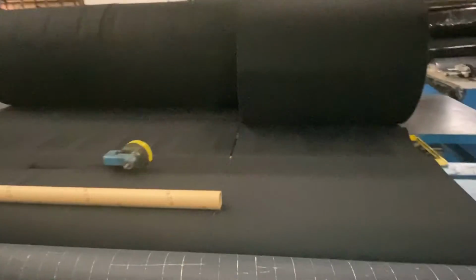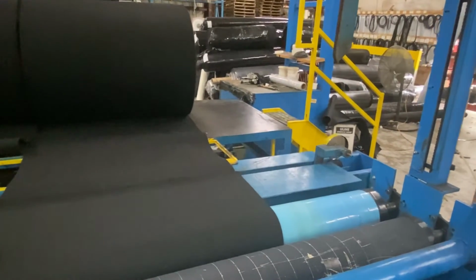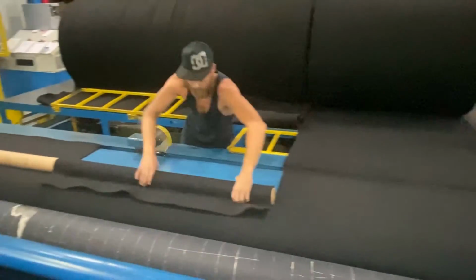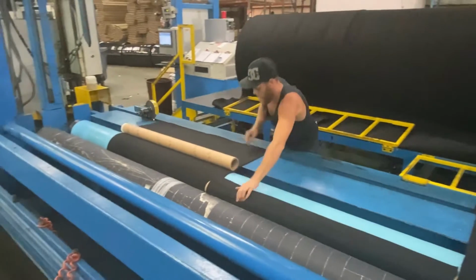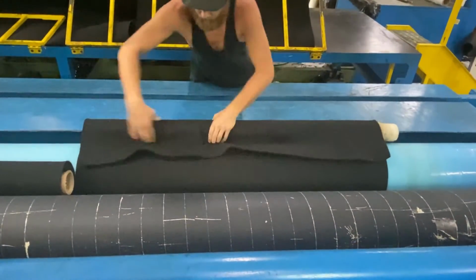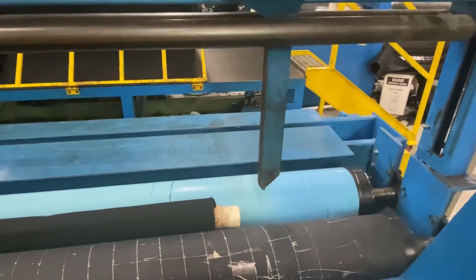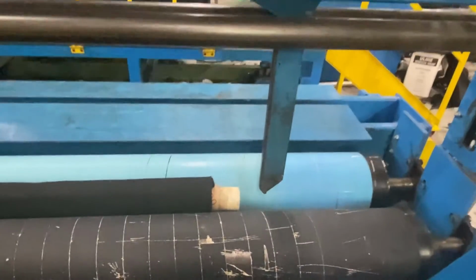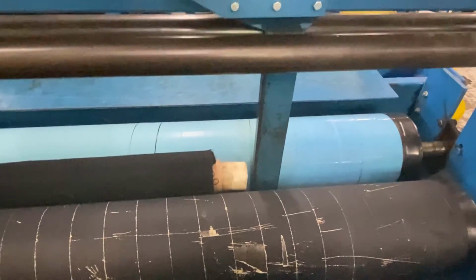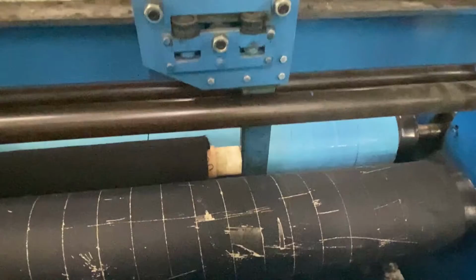The cross-cut blade will then cut the tail across the width of the material, which will detach the roll. Use precaution while the cross-cut blade is in motion. Remove the core inserts and place a new core on the top of the remaining tail of the fabric. Wrap the tail around the core and in a rolling motion towards the middle of the pull and packing rolls. Repeating the same process as the previous roll change, also repeat the steps of position the core guiders and lay down roll, and then start the winder up to begin building material on the core.